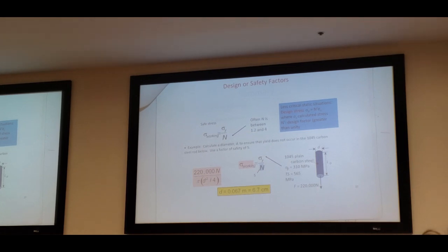If the tensile strength or the yield strength required is given, for example, 100 megapascal, and for a given application, use something with 150 megapascal yield strength. So you are sure that it is strong enough to sustain that load or whatever application required. You got it? That was the 20th century approach.